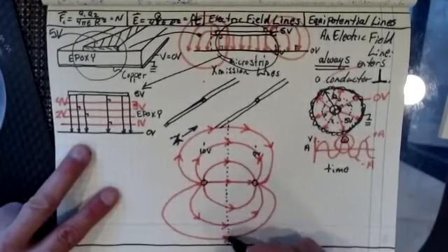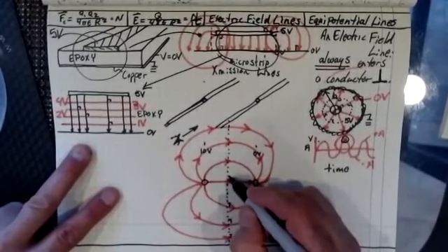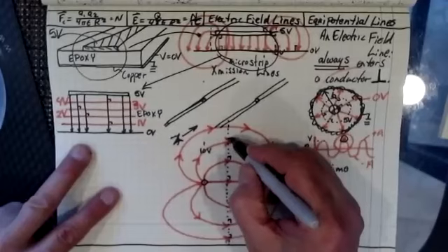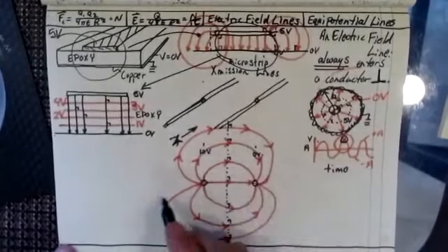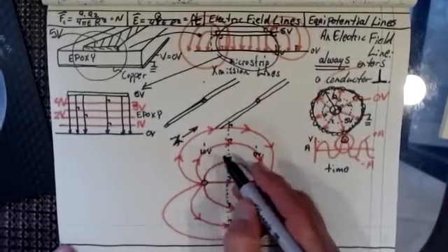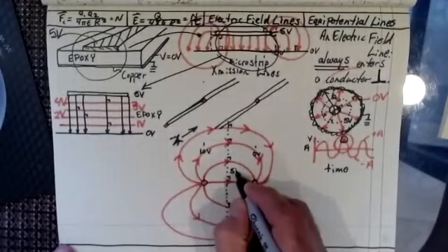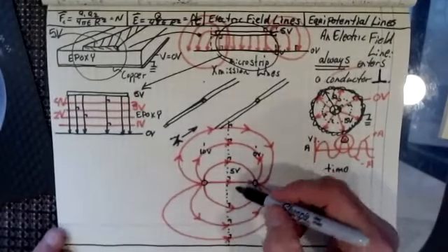All of those are perpendicular, well, they're supposed to be drawn perpendicular to that line. So that would be an equipotential line. Now, what equipotential line would that be? This is 0 volts, that's 10 volts. So there would be my 5-volt line, wouldn't it? Does everyone see that? Now let's do another one.